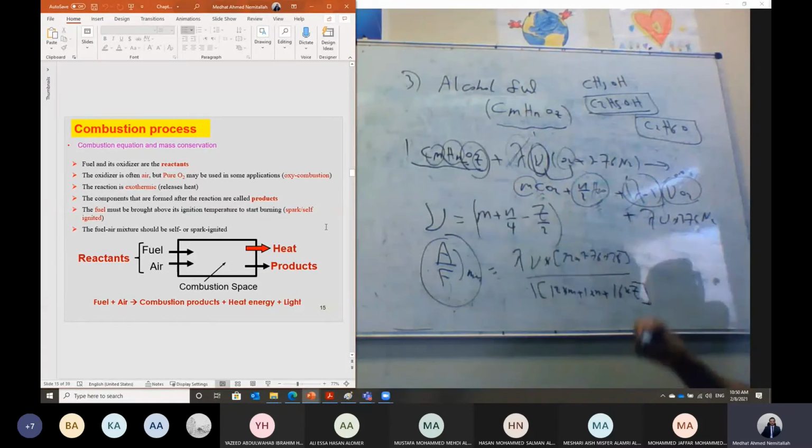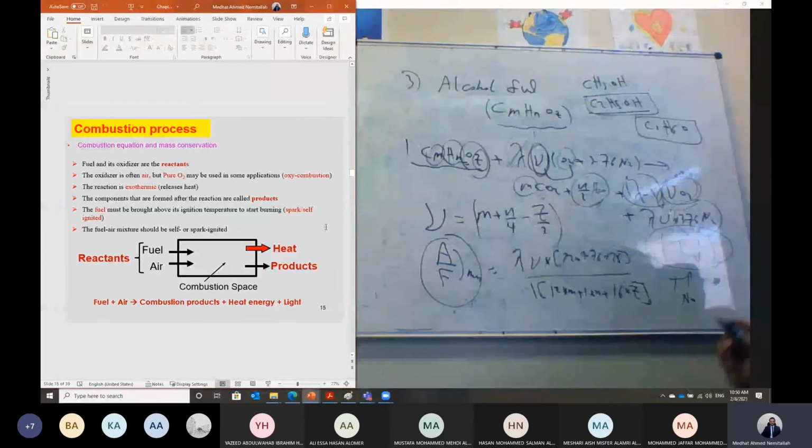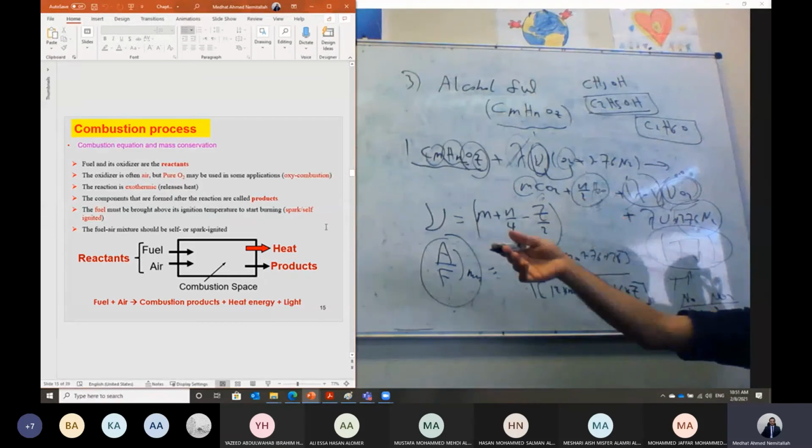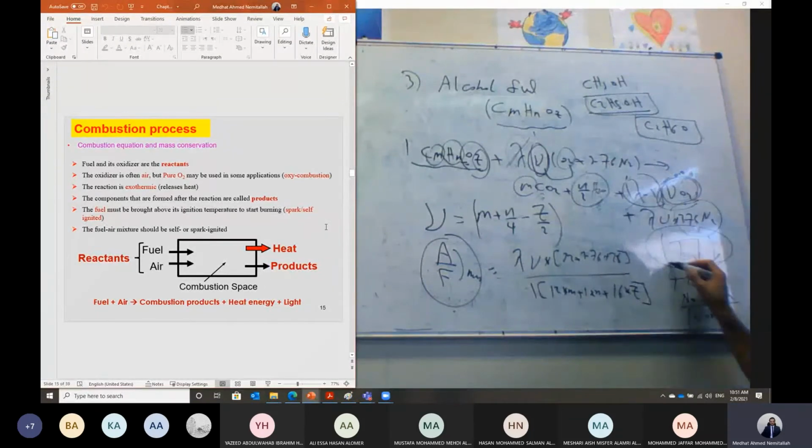Plus, we may have excess oxygen, plus for sure excess nitrogen. That should cool down the combustion product. It should reduce the temperature of the combustion product. And this is a parameter, Shabab, to control the emission. Because usually at higher temperature, as I told you, nitrogen will dissociate to NO plus NO2, and this should result in NOx emission. One mechanism to reduce NOx emission is to burn using excess air. We can add more air in the combustion process, so we will have excess air in the combustion product. It will cool down the temperature of the combustion product.